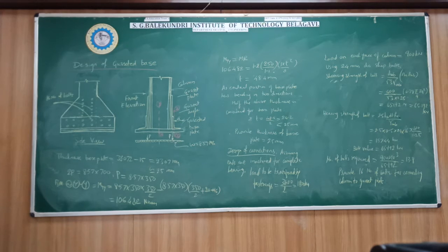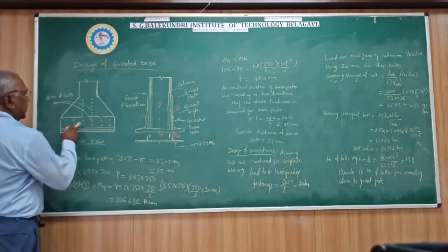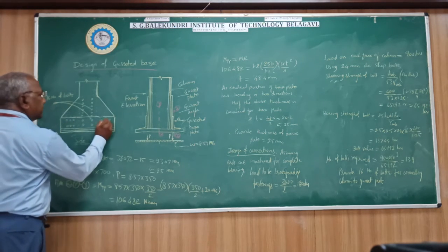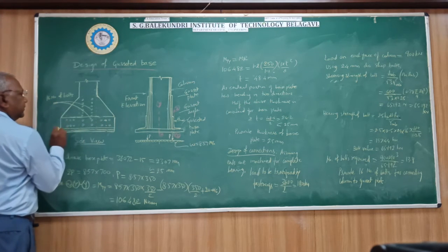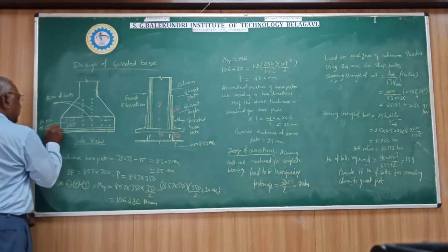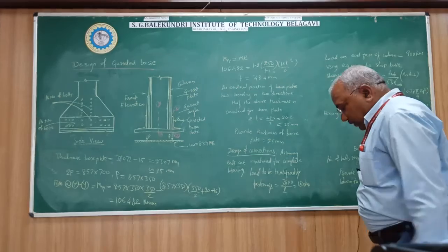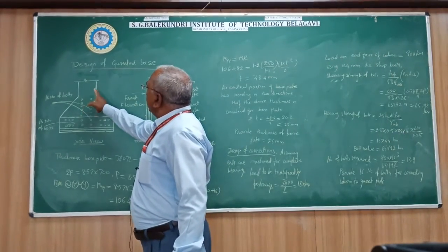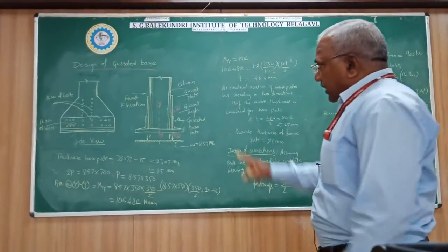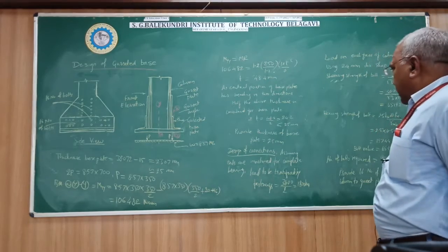Okay. So here the same number of bolts is also required to connect the gusset angle to the gusset plate. So here there will be another 2 lines of bolts like this. So these are also 16 number of bolts. So 16 bolts are required to connect the gusset plate with the column, and the same number of bolts are required to connect the gusset angle with the gusset plate. In the side view, we can see the bolts required to connect the entire assembly. So this is the design procedure.